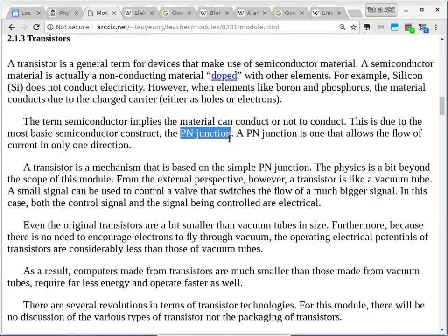So to turn it into a conductor, we introduce phosphorus or some other material. That phosphorus has 5 outermost electrons. If you put a very small amount of phosphorus into silicon as it cures, the phosphorus is forced into the crystalline structure. But there's a problem, because phosphorus has 5 outermost electrons. The structure is going to use up 4.